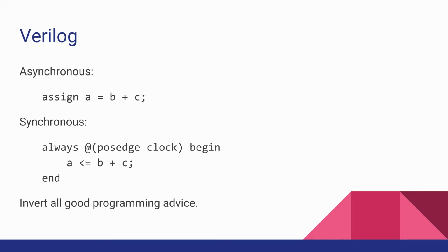So then you have to run it a lot lower. And what happens is that the tools that you use, the compiler, knows how fast that happens. And it knows how it laid it out, and it knows how far everything is, and how far everything has to propagate, and how fast it propagates through the adders, and all this stuff like that. So it knows this, and it knows how fast your clock is. And if you speed up your clock too much, and you do something too complicated here, like a big multiply, it'll tell you at compile time. It'll say that won't work.